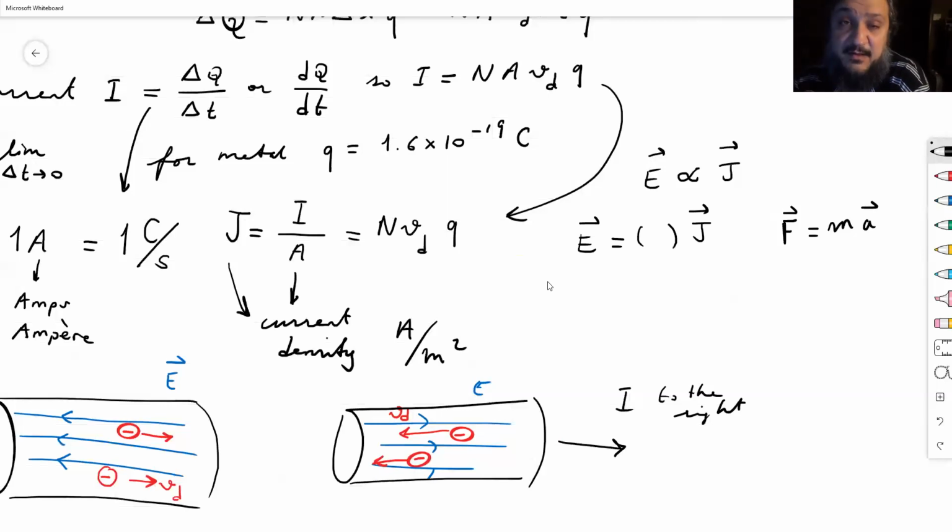Now, why would you have that resistance? Well, it depends on many things, okay? It depends from metal to metal, of course, from material to material. It depends on things like temperature, because although those ions have fixed places in a metal, they're in a constant vibration because of their atomic nature, all right? And that vibration means energy. So if you give energy to the system by heating up that metal, they're going to shake more violently, okay? And when the electrons are trying to pass through those vibrating ions, they will have a difficult time, right?